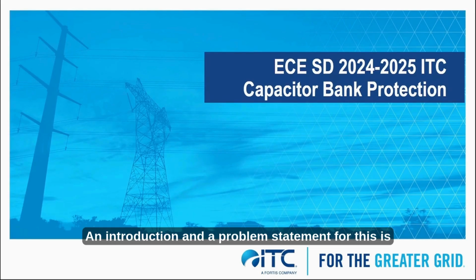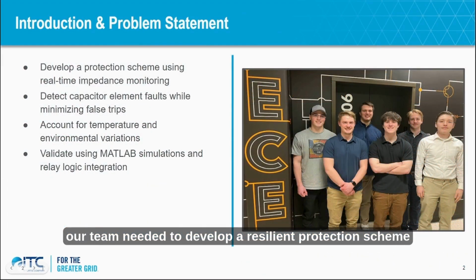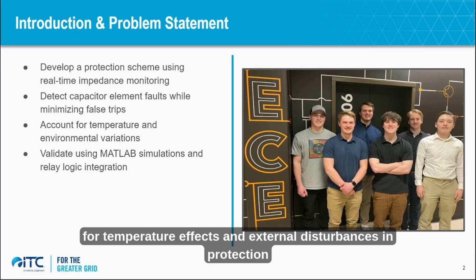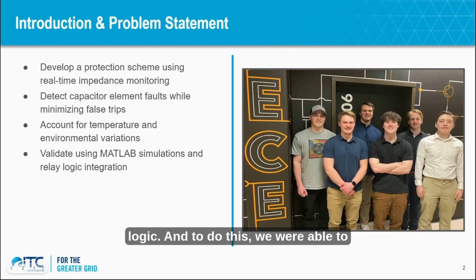An introduction and problem statement for this: our team needed to develop a resilient protection scheme for capacitor banks using real-time impedance monitoring. This would enhance fault detection accuracy by analyzing impedance variations and reducing false trips, as well as improve reliability by accounting for temperature effects and external disturbances in protection logic. We were able to validate it by using MATLAB and Simulink and testing with relay integration.